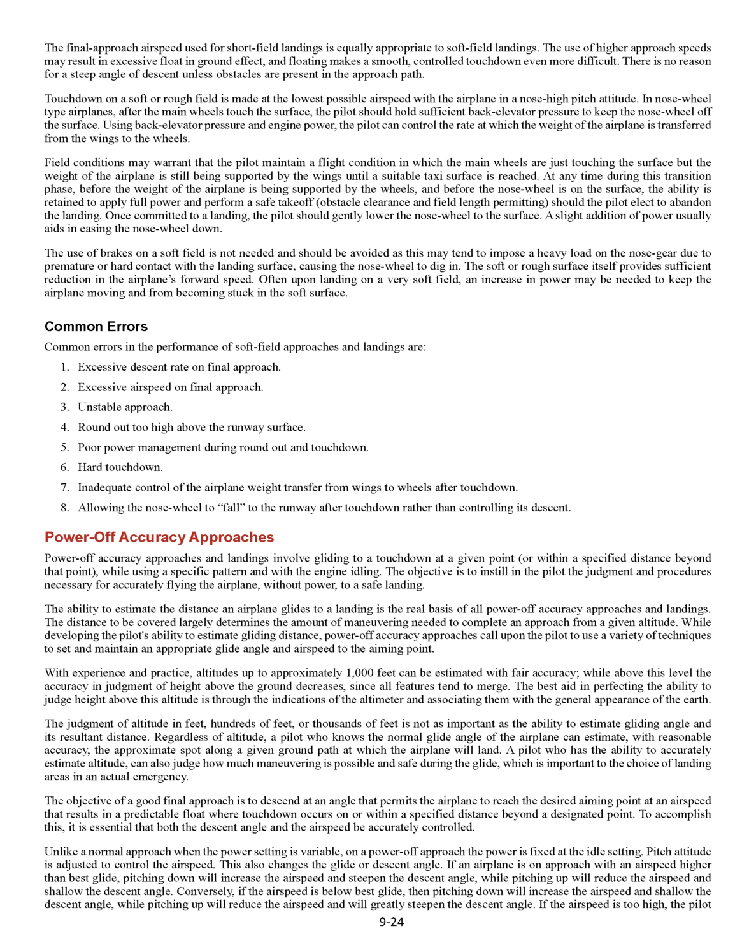The best aid in perfecting the ability to judge height above this altitude is through the indications of the altimeter and associating them with the general appearance of the Earth. The judgment of altitude in feet, hundreds of feet, or thousands of feet is not as important as the ability to estimate gliding angle and its resultant distance.